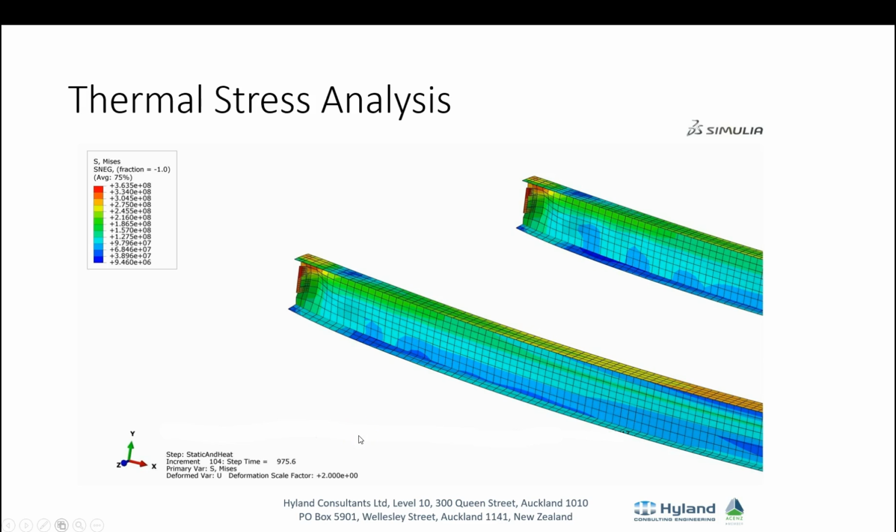Okay, so we then do the thermal stress analysis, and what that shows here, for example, is the cleats and the ends of the webs get crumpled, and we get failure developing there. So we get combined stresses, in the von Mises, greater than what is allowed.